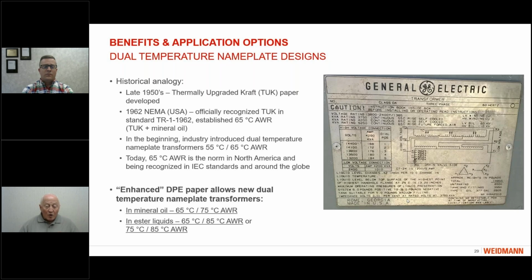So again, to draw the analogy with what we are discussing today with enhanced DPE paper, we can say that it's possible to design dual rating or dual temperature transformers with 65/75 Celsius in mineral oil, and 65/85 or 75/85 average winding rise in ester liquids. Next, please.